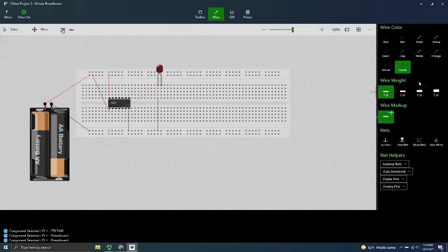And I'm going to use another one. Let's try. We haven't used blue yet. Okay, there's blue. The second input right here. Now, I can connect it to ground, which would be 0, or I can connect it to over here, the positive side of the battery source. Let's go ahead and do the ground first, right? Like that. Okay. And we are actually done with our connection of this circuit.